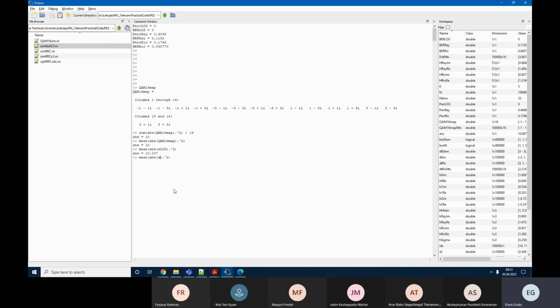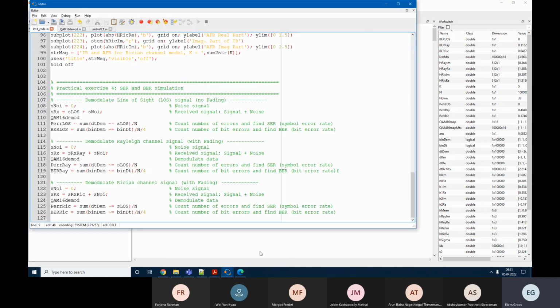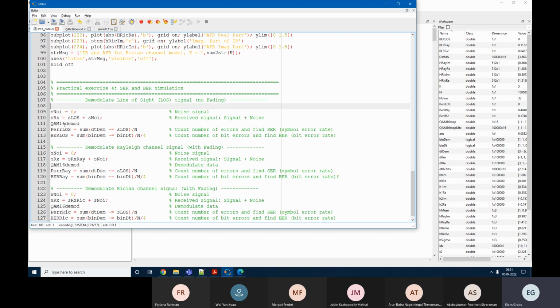So for Gaussian and Rayleigh channels, in fact, we have some attenuation, impulse response, reflected signals, which change the value significantly, yes? And for the Gaussian channel, it's even below, right? So we need to consider the actual average power of the signal we have received. For that reason, we need to calculate this power for each of these three signals before we calculate this noise. So that would be per signal loss.